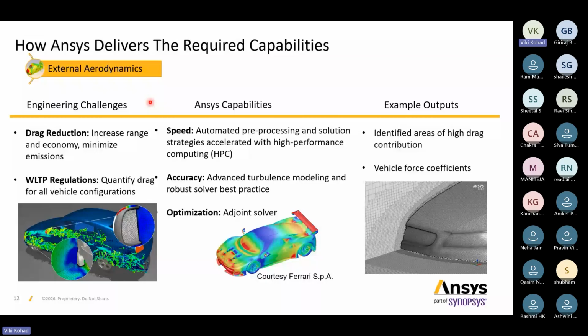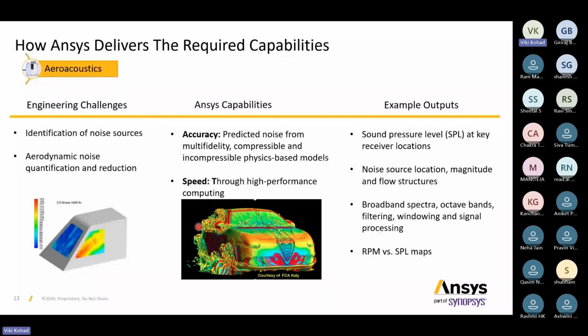These are the external aerodynamics aspects. Like this, you can use external aerodynamics, like in Fluent, you can set up the vehicle, flow the air over it, and check it. The aeroacoustic part is also there because of the air. Air is like a noise source. Whenever that air gets stuck in any part of the electric vehicle or the exterior, sound gets generated. It is based upon the velocity of your vehicle, and also on the air temperature at that particular point.